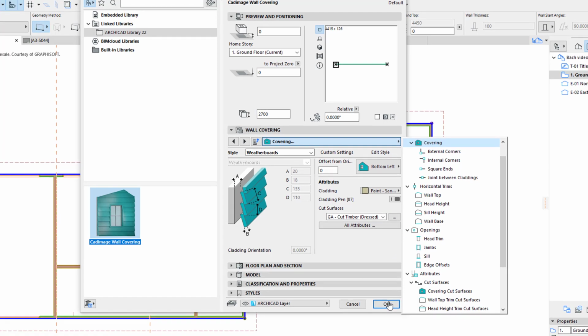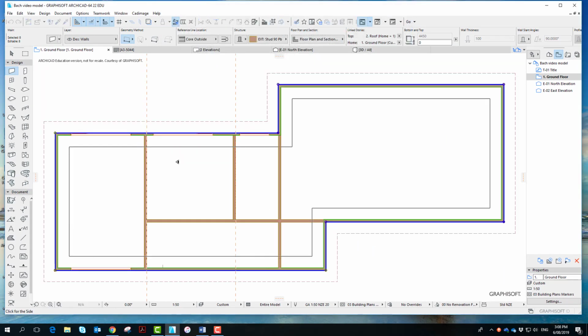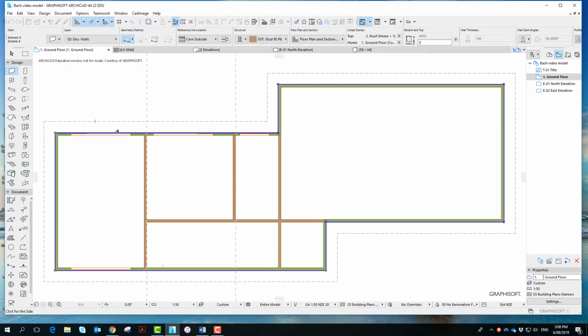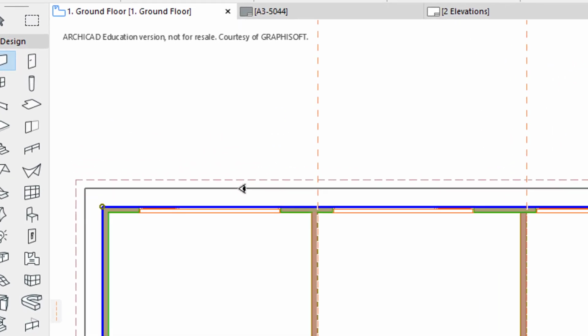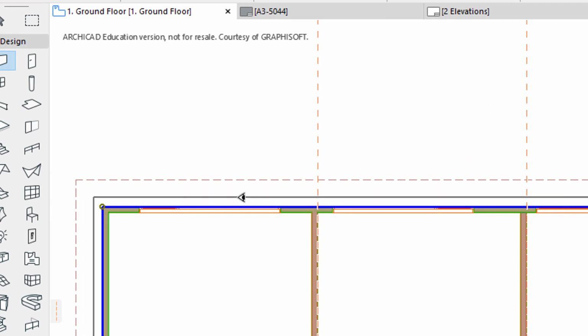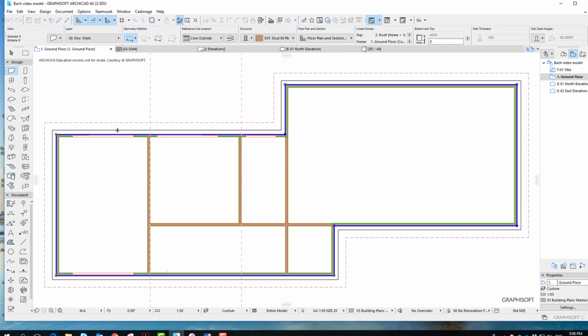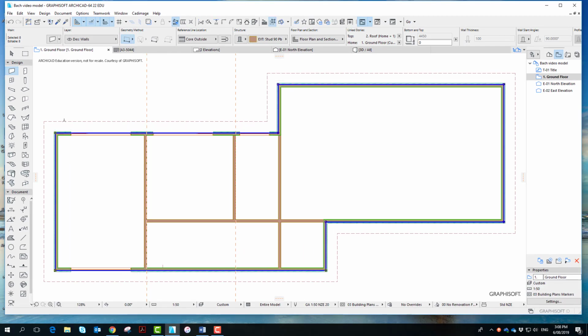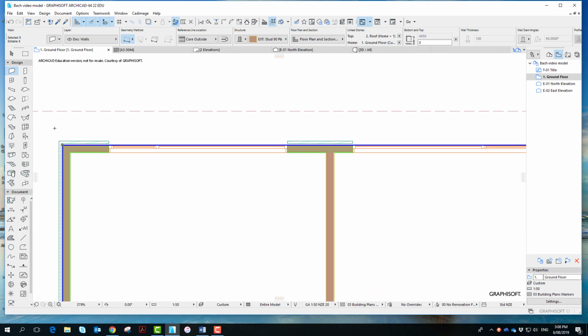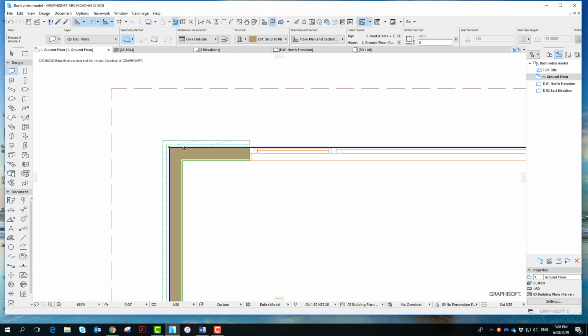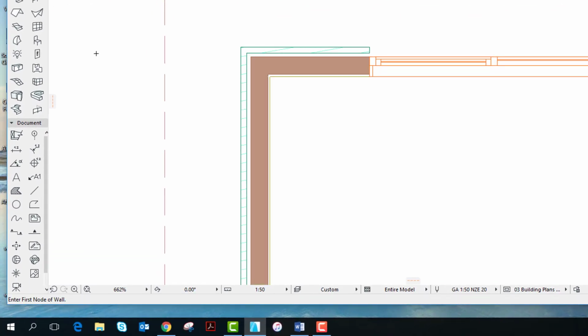So if I click OK, and then as I go, you're getting this kind of offset thing. Don't click inside. Make sure the little eye is to the outside, and it does not matter how far away, because it's going to put it right close to the wall we've modeled already. So just click. And once you zoom in, you'll see that as well as the selected walls, I'll just deselect, you've got this little even cavity and this new element that's been produced.